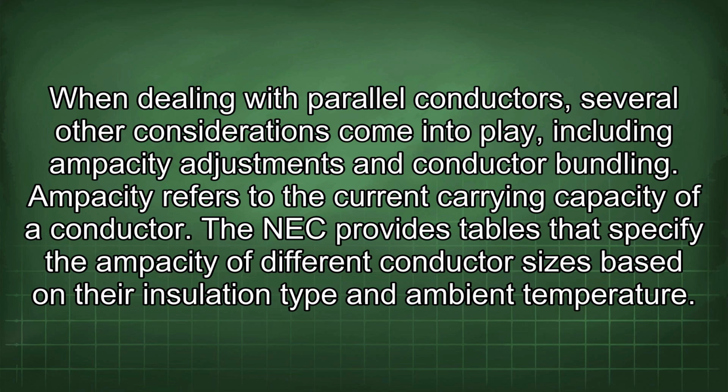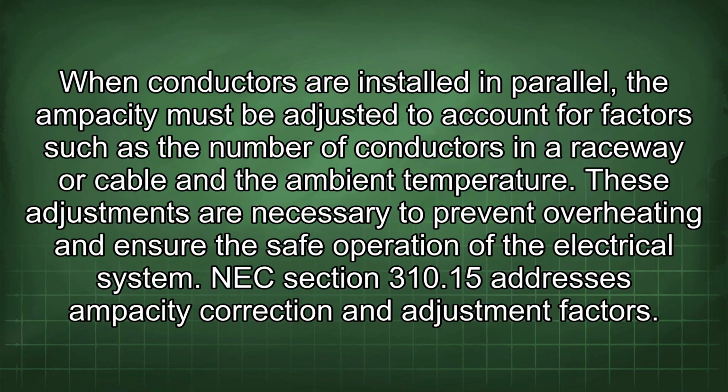Ampacity refers to the current carrying capacity of a conductor. The NEC provides tables that specify the ampacity of different conductor sizes based on their insulation type and ambient temperature. When conductors are installed in parallel, the ampacity must be adjusted to account for factors such as the number of conductors in a raceway or cable and the ambient temperature. These adjustments are necessary to prevent overheating and ensure the safe operation of the electrical system.